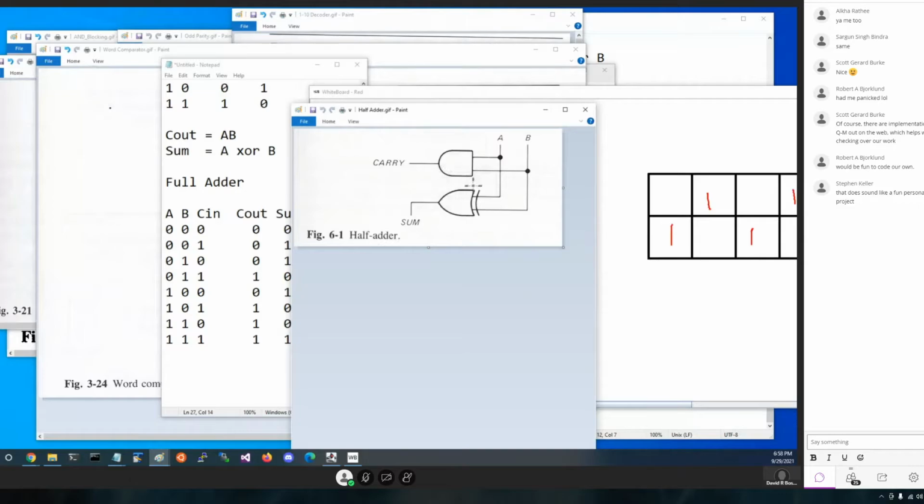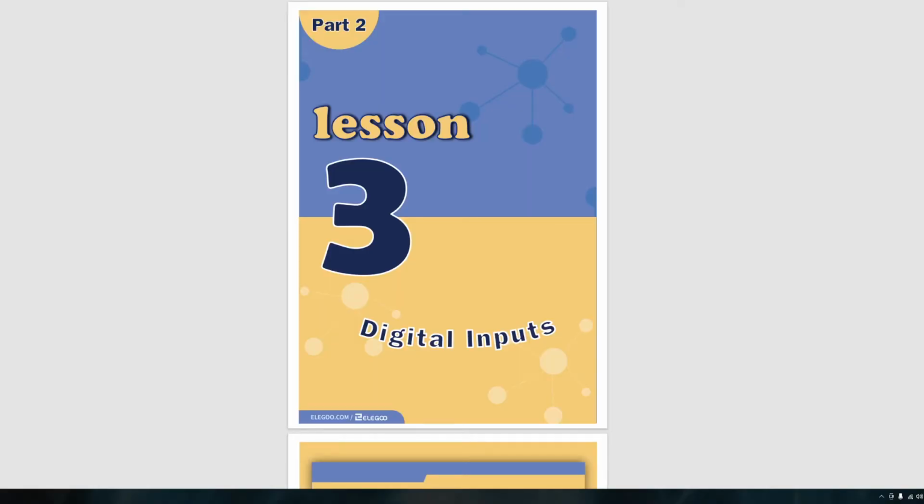Now, if we were building this out of 2-input NAND gates, we'd of course have to turn this into NAND gates, but it takes 5 gates to do, but we could make it happen with our sum of products logic. So this is a circuit we would use if we needed a half adder, the right column or single column of addition. We saw also, though, for the next column and those that follow, because we may have a carry in, we might need to have a full adder.